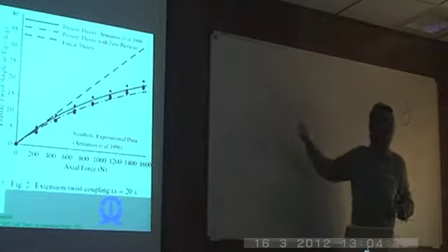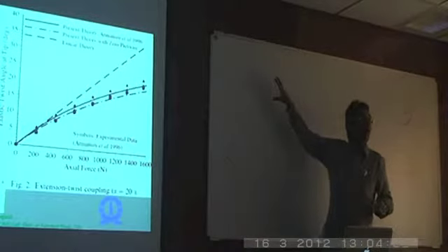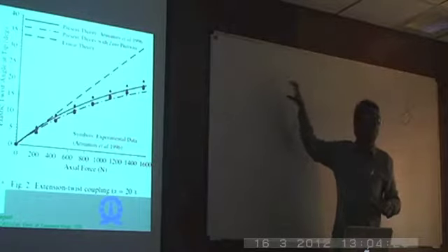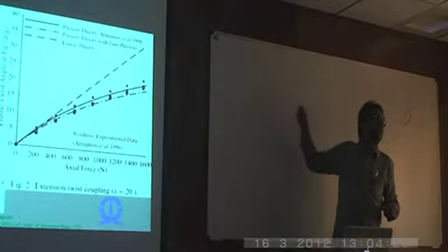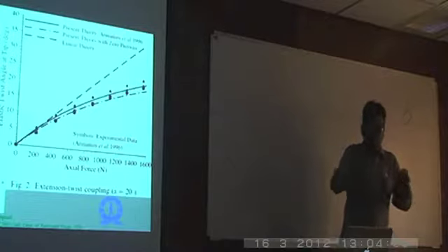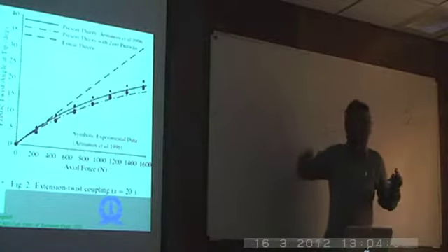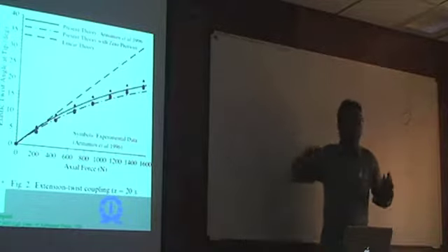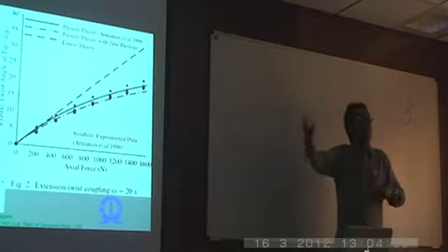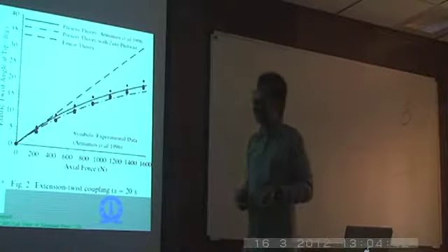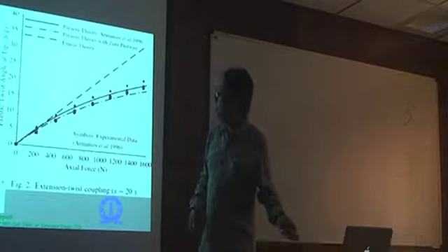Whether it is a constant or not, even if it is a constant, there is an extension twist coupling. But what is more significant is that S12 is no longer a constant. It is a function either of your extension strain, gamma 11, one way of looking at it, or in terms of kappa 1 itself, or again the pre-twist value small k1. So it's a function of all of those things.